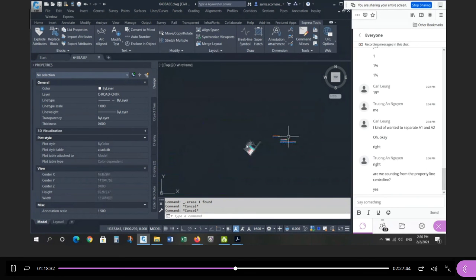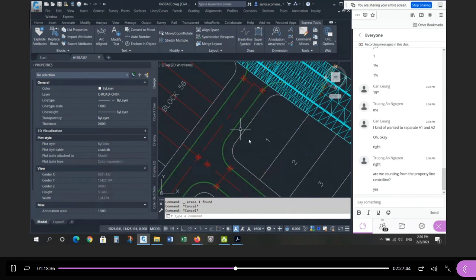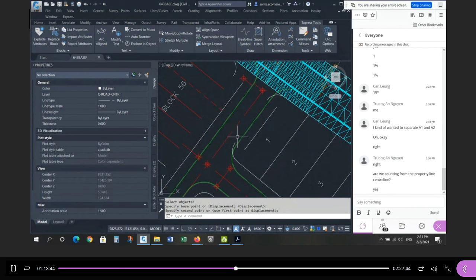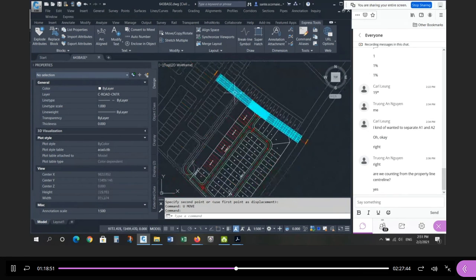The other thing is now suppose, we're not going to do this, but suppose the designer comes back and says, oh, you know what? We're going to move the road. We're going to shift it down here by 1 meter or 5 meters. Right? Well, then you need a new elevation to start with. It's already there. All the elevations of the road you're connecting to are there on that surface. So if you choose to design it somewhere else, if you shift your design location, you can quickly get the elevation that you need to connect to, the location and the elevation that you need. Right?